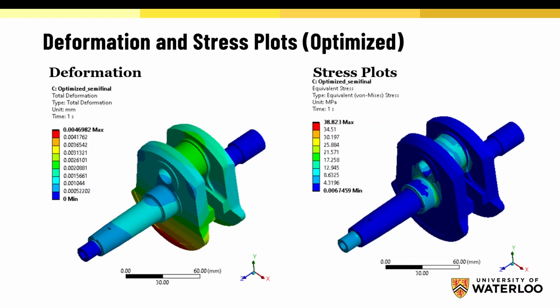You don't really have a good solution, but you might have test results that say, okay, I'm undershooting my temperature target or my temperature experimental value. Why is that? What ingredients to the model will make the temperature go up? Which ones will make them go down? And then you kind of tune it from there to suit. But it's an excellent question, and even now I don't have a silver bullet answer for you. It really takes time.